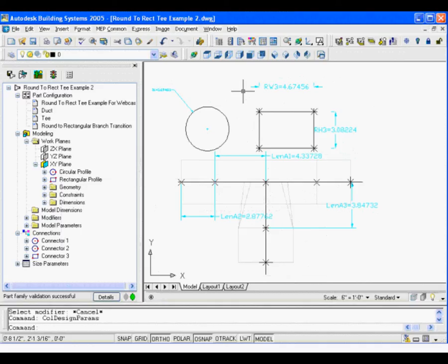So the best way to do that is to open up Content Builder, search through the front end of Content Builder, navigate through the catalog, select a part, and see if it can be parametrically modified. We have some legacy content in here that you will not be able to modify. So that's the best way to find out if it's parametric parts that were built with Content Builder.